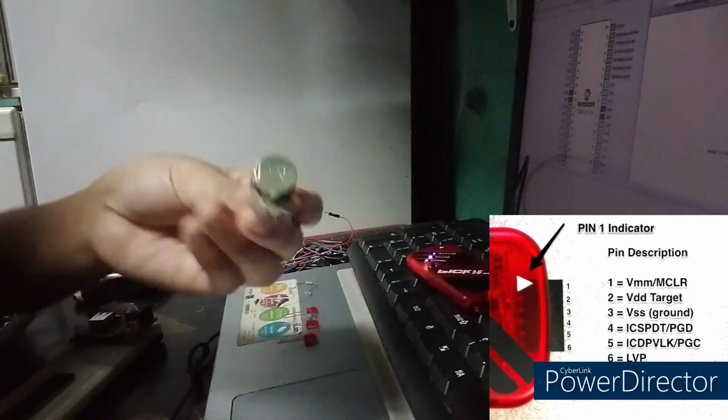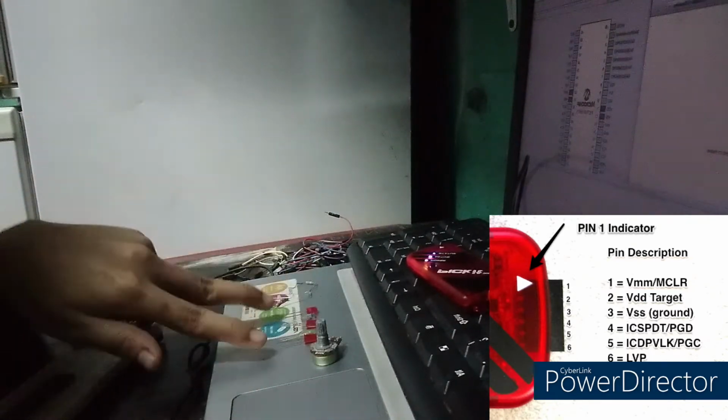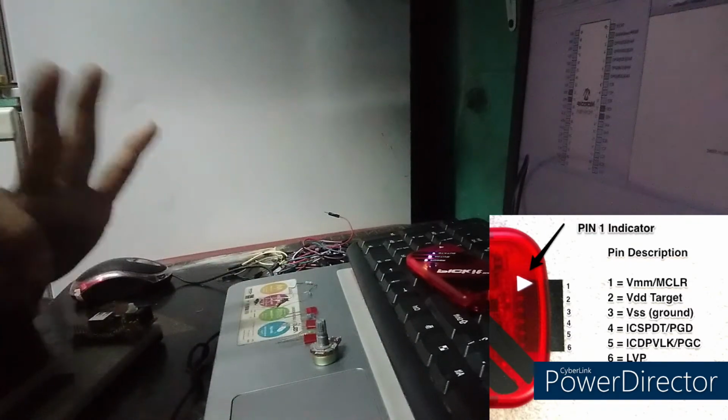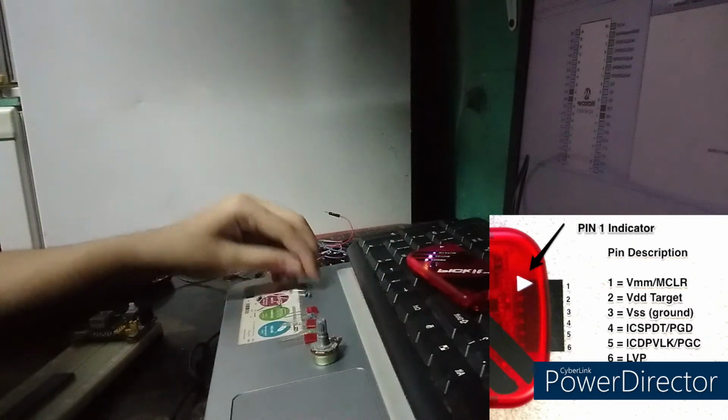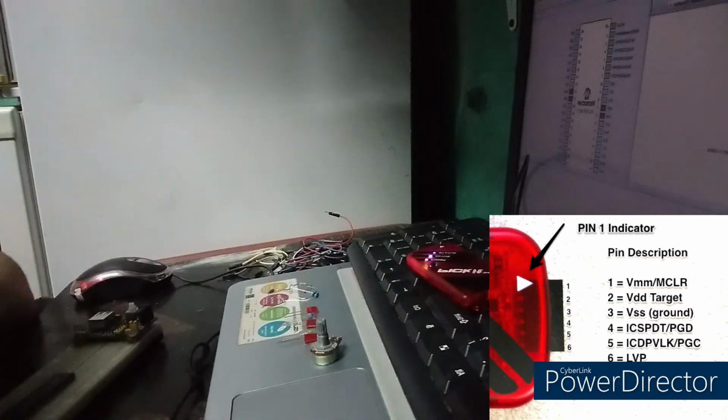For our circuit, we will be using our potentiometer as our analog input, and then our 5 LEDs here, which will be 3 color red, okay? That will be our indicator for level 1, level 3 and level 5. So these are the extremities of the level of our electric fan. Then we will be considering level 2 for the green LED, then level 4 for the blue LED. So we will be needing 5 resistors, 360 ohm resistors, which will be connected to our 5 LEDs.